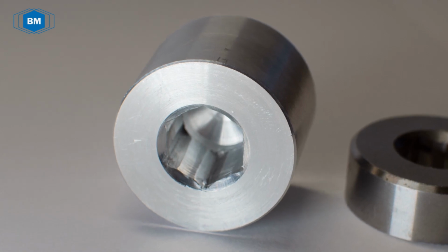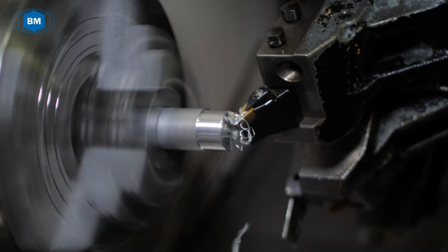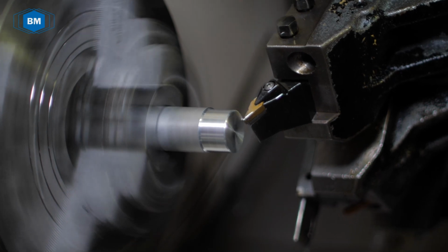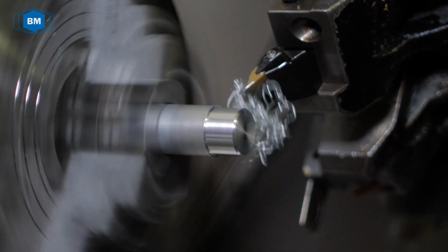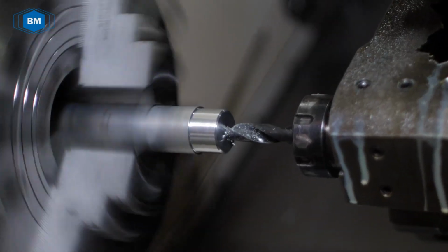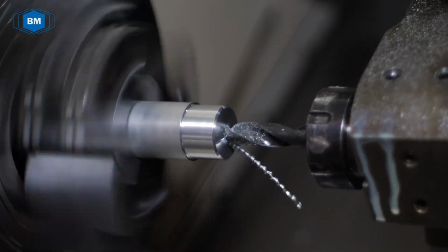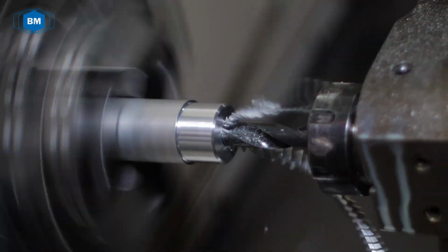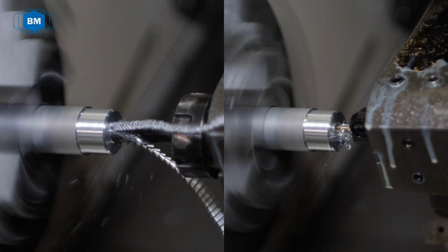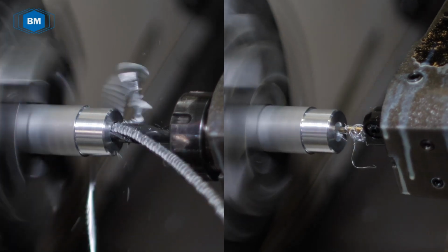Let's take, for example, the creation of a closure cap, at the end of which a hexagonal figure is created to allow the cap to be tightened. Since the figure to be made is hexagonal, before proceeding with the broaching tool, it is necessary to perform a pre-hole with a slightly larger diameter and a chamfer that covers the maximum vertices of the polygonal figure.